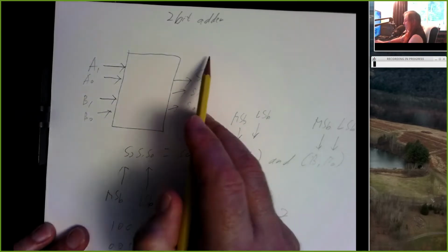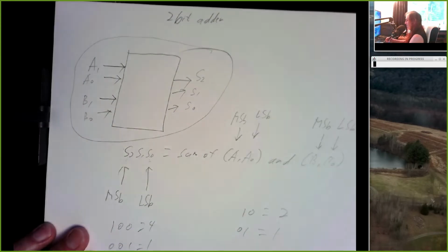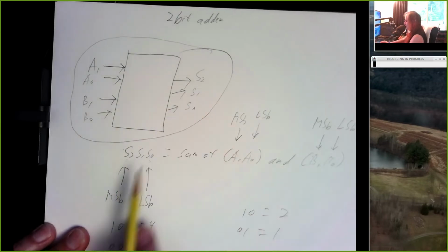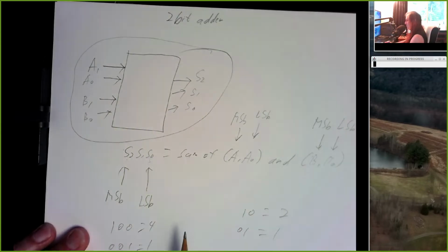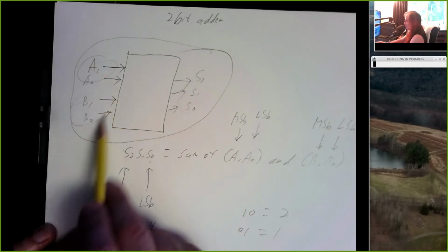So it's really important when you sketch your system diagram for your lab or for anything else that you know what these 3 outputs are. Because just saying S2, S1, S0 does not in itself tell you that S2 is the most significant bit, so make sure you indicate that somewhere. And of course indicate that this is the sum of this number plus this number.